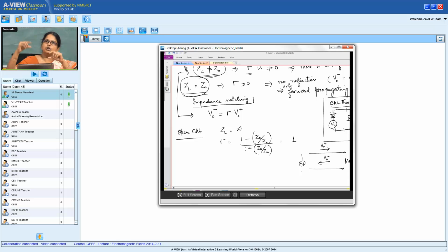If you do not load the circuit, let's say you made a high frequency voltage oscillator for your project, some 3 gigahertz oscillator, you struggled and made your 3 gigahertz oscillator. But if you do not take care to load that before you turn it on, this voltage is going to go back into your oscillator. And if the oscillator does not have enough isolation, the IC does not have enough protection, it is going to damage the oscillator itself, because the entire voltage is going to go back into the IC. That can simply damage your circuit.